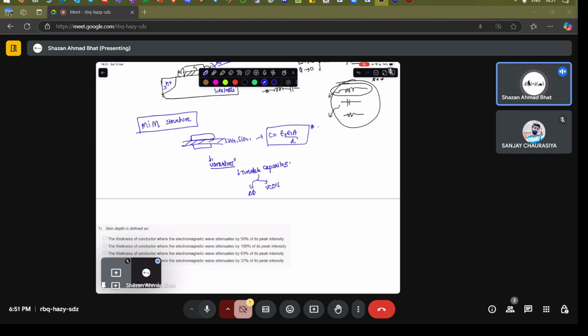Depending upon the capacitance value, let's say for example, you can tune the capacitance from C max, and you can lower the capacitance to a minimum of C min. You can tune the capacitance value between some maximum value and some minimum value. Then there is something called the tuning ratio, which is the ratio of C max over C min. It shows how good you can tune these capacitors to control the delays, time delays and other things.